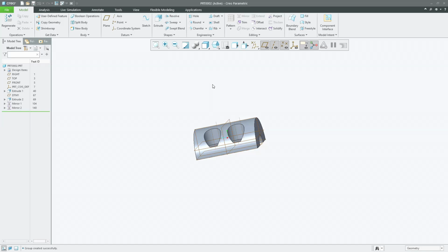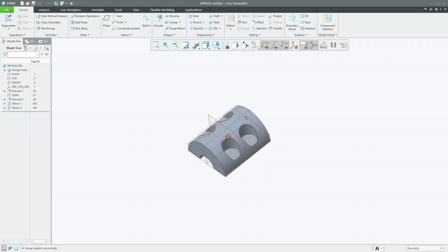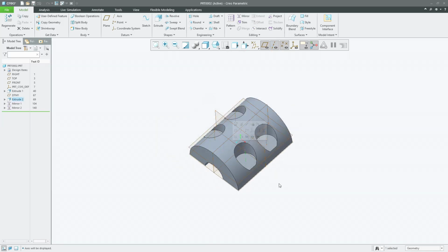So now the next part is I'm going to have a hole on this area. To have a hole, I'm already having an axis line here, which is automatically created when we create this extrude. In this same hole axis, I'm going to have another hole with the diameter of 0.25 into d plus 2. The 0.25 into d is 7.5 and plus 2 is a total of 9.5.